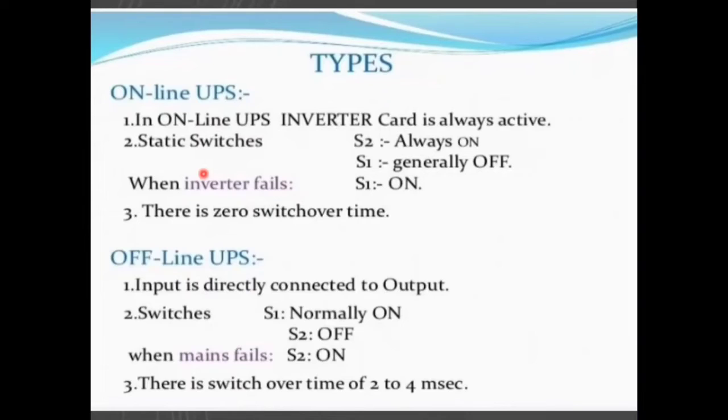Okay, at first, online UPS. Online UPS system is very essential nowadays. In this UPS system, the online UPS system is normally on, and the load is fed by it through a static switch. In case of a fault in the inverter, the load is fed through the bypass static switch.